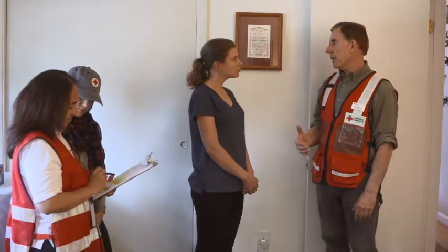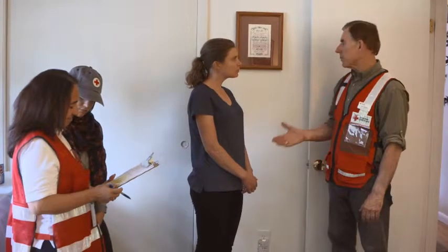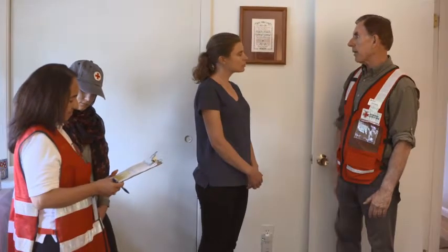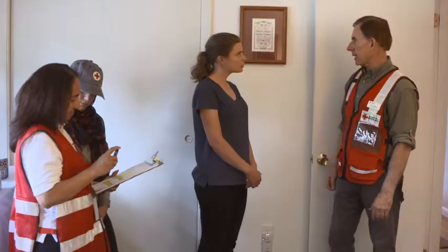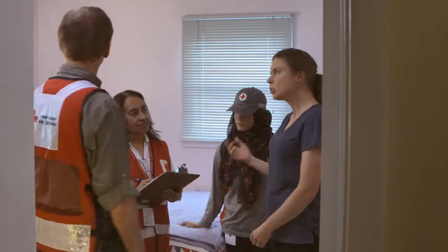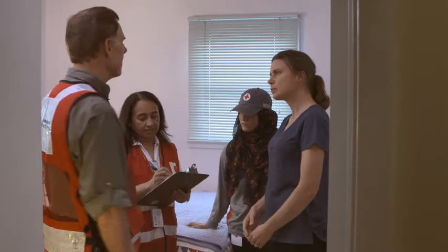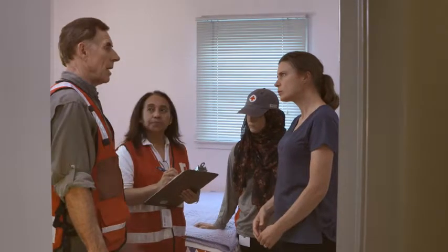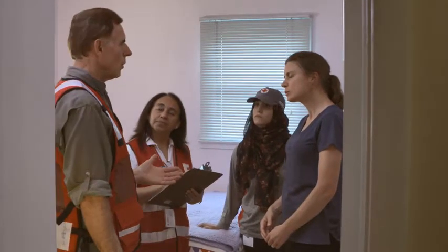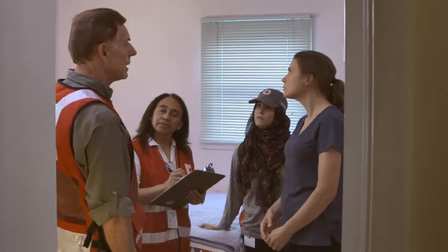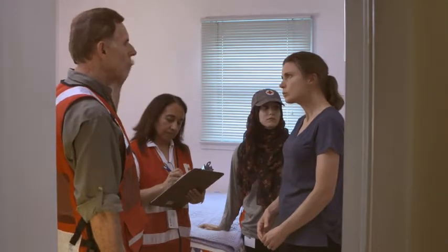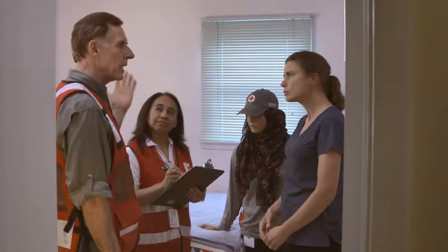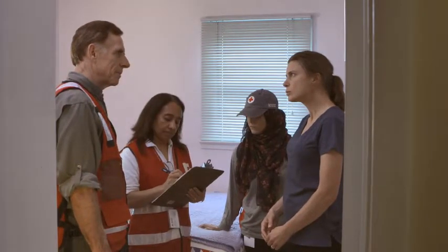Presently, there is no smoke alarm in your youngest son's bedroom. It is recommended that a smoke alarm be placed in each bedroom and sleeping area, ideally on the ceiling. And this is the master bedroom where my husband and I sleep. Okay, so presently you and your husband's bedroom has no smoke alarm. Here also, installing a smoke alarm is advisable close to the center of the ceiling where there are no heating vents, cooling vents, or fluorescent lights that could impede the operation of the smoke alarm.